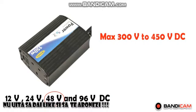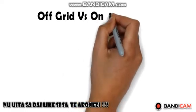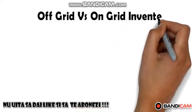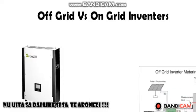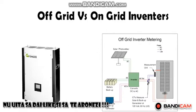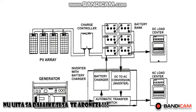Now that we have introduced inverters, let's have a look at the most common question asked about them, that is, what is the difference between an off-grid inverter and an on-grid inverter? Well, an off-grid inverter is a product that works completely isolated from the grid. It has no provision to tap into the grid electricity or feed electricity to the grid. Normally, if a PV system is designed with an off-grid inverter, then the panels are connected with a charge controller. The charge controller is connected to the batteries. The batteries are then connected with an off-grid inverter.